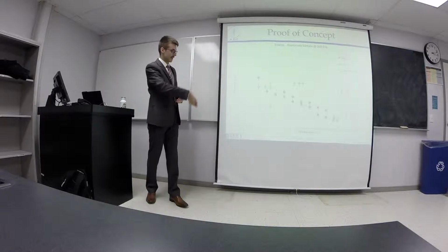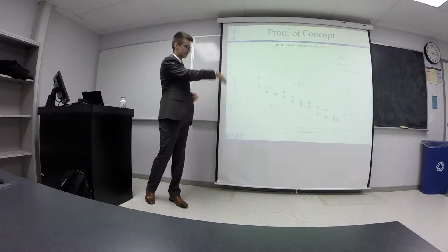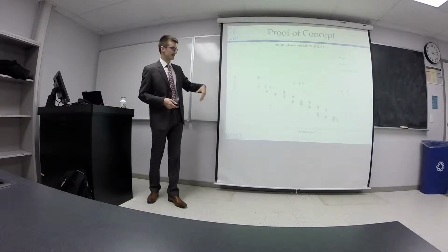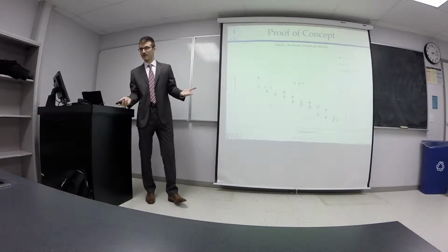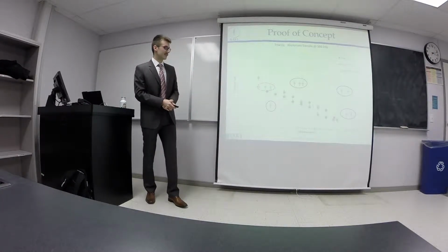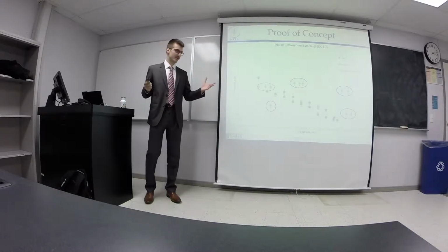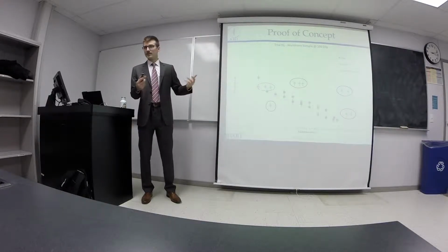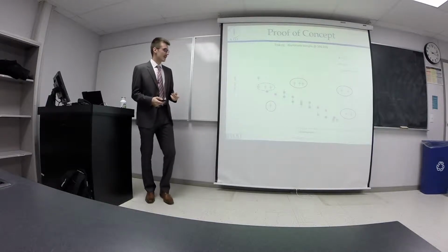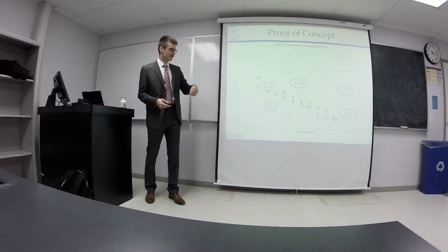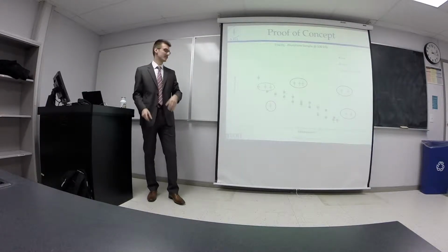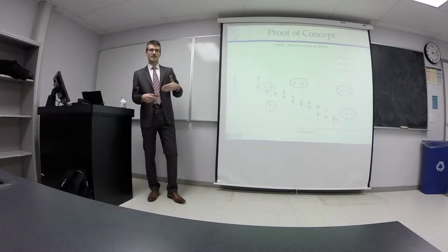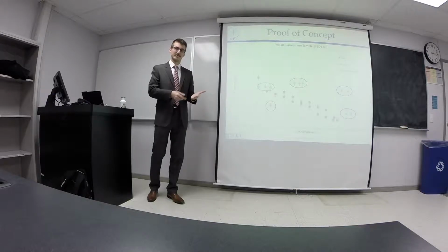So basically what happened is I would run this probe widthwise across the sample, and whenever it detected something, it would produce an audible beep. I would mark down the location of that beep, and then I'd superimpose it on this graph to see if it lined up with where the cracks and flaws are. So as you can see, there's kind of like a grouping in terms of how the points were generated. You can see the ones that have the solid circle around them, they look like air gaps. That's what I concluded, just because of the distance from the crack and the kind of local nature of them. But these ones here that are in the dashed line are almost right on to where the crack and flaw are. So this may be indicative of an actual crack or flaw detection of the probe.